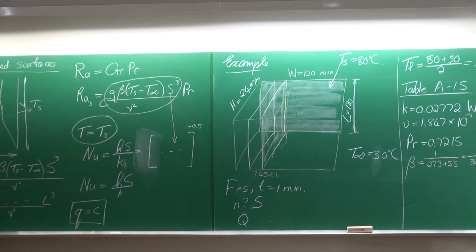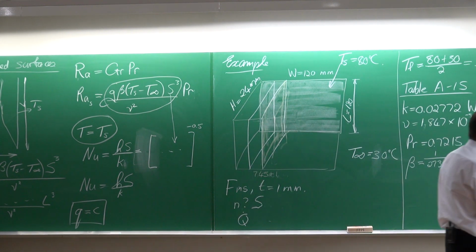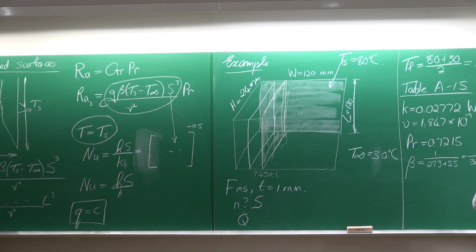12.8 fins. We cannot use 0.8 of a fin, so we are going to use, in this case, no, sorry, I keep on making a mistake. So, sorry, this is 13 point something, one other value larger than 0.5, so we're going to use 14 fins on that surface.